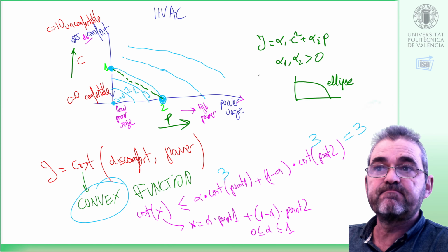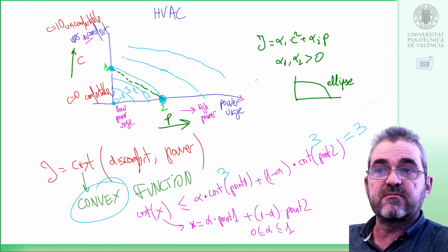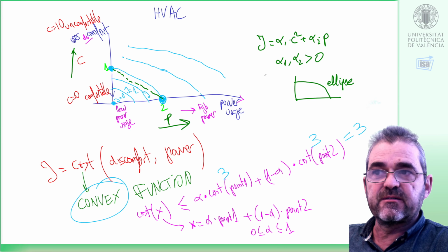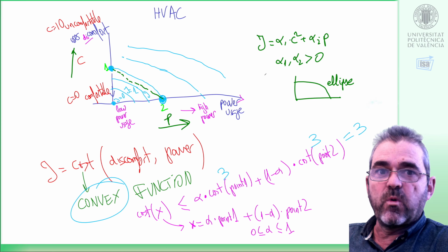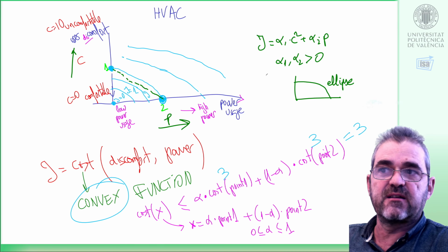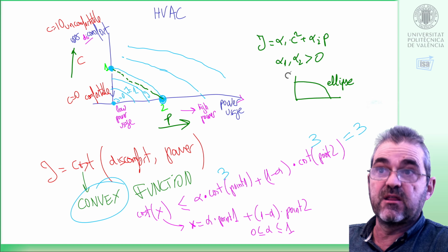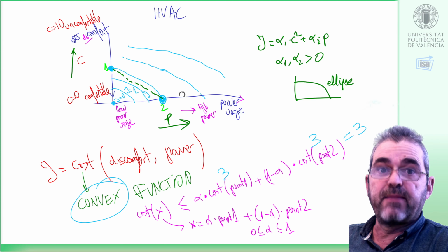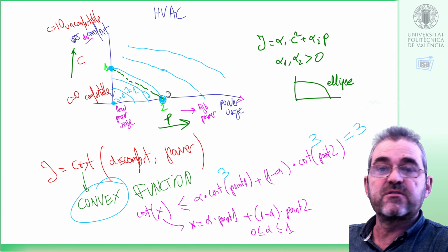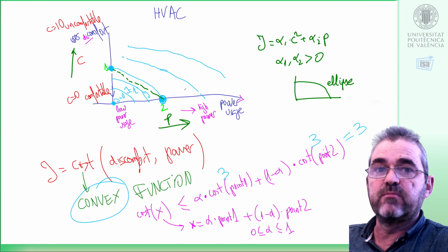It's important to note that these plant optimizations, in many cases, are the lion's share with respect to the global efficiency and profitability of the plant. Myself, as a control engineer, I'm used to think that tuning a regulator so that a gain is 7 or 8 or 6 is a very important thing, but maybe the money is in these optimizations on the power usage and temperatures to pursue instead of the time constant of the temperature control.